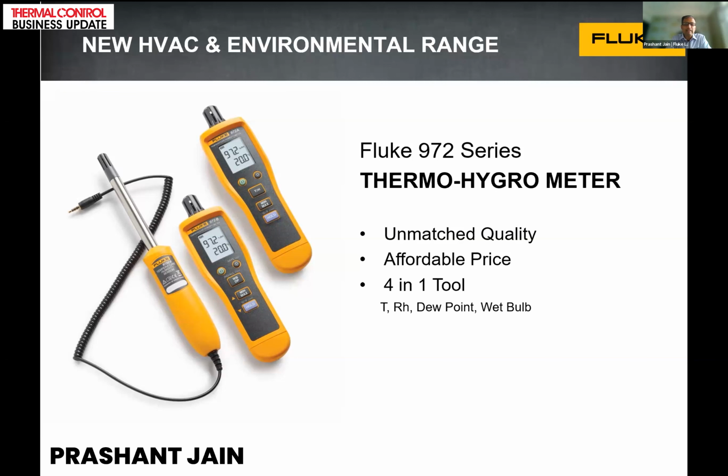So spot testing actually helps us measure multiple points in a building, because these are all handheld instruments. We can roam around, we can move across the floors, across the rooms, across the halls, across the lobbies using these instruments. And generally what I have seen, being in the test and measurement industry for more than a decade, is that with these instruments the accuracy and the calibration is much easier compared to a fixed type of sensor. So these handheld instruments also sometimes help us check whether our fixed sensors are working right or not.